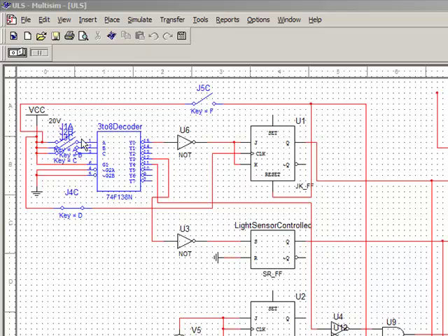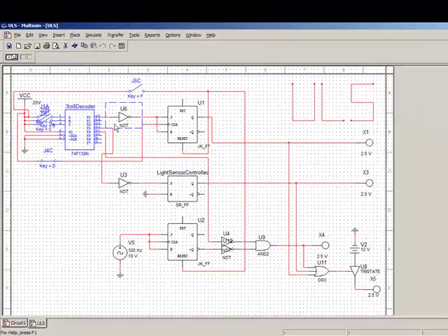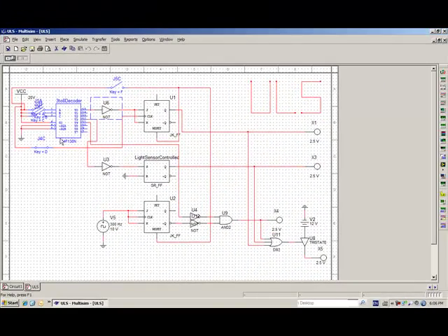So we have to trigger this input of the latch or the flip-flop, so we will activate it. So 000 as the input for ABC will trigger the first output, Y0, and as we can see from the bubble here, it's a logic 0, so we have to put an inverter or NOT gate.